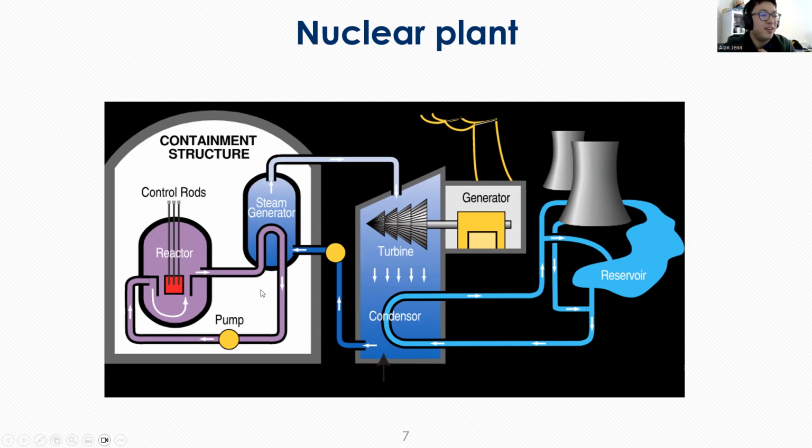Maybe this is kind of obvious, but the water in the second closed loop is highly radioactive. And so we do this so that you're not sending radioactive material through your turbine. That would make maintenance of that part of it a lot more difficult. Okay. And so that's kind of the high-level technical elements of how a nuclear plant works.